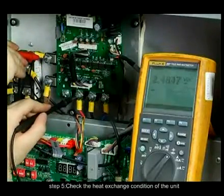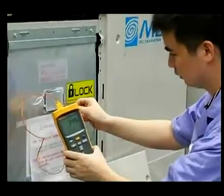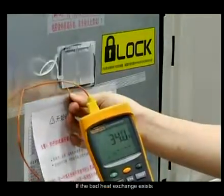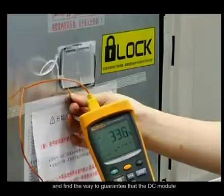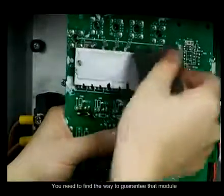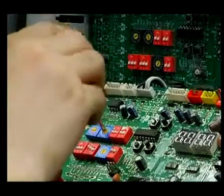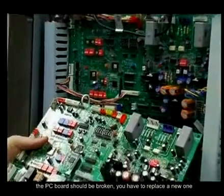Step 5. Check the heat exchange condition of the unit. Bad heat exchange will lead to high temperature inside the electronic control box, which can lead to DC module protection. If bad heat exchange exists, you must improve the heat exchange condition and find a way to guarantee that the DC module can work in the normal temperature range. For example, wipe the thermal silicone grease well. After the above repairing, if the malfunction cannot be solved, the PC board must be broken. You have to replace it with a new one.